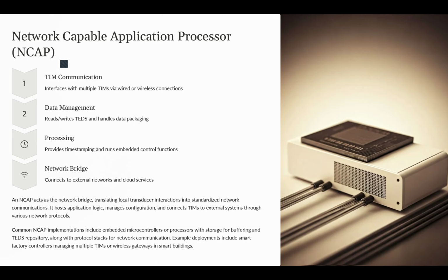And this NCAP basically reads and writes the TEDs, so it allows the system to identify each sensor or configure the acquisition settings and maintain and record each device's specification and status.